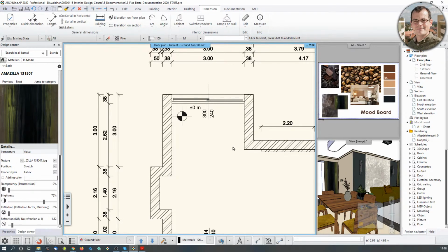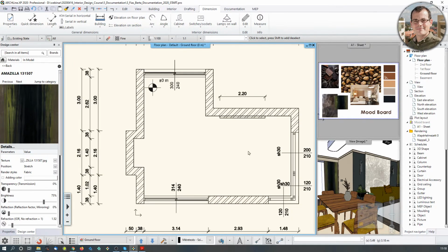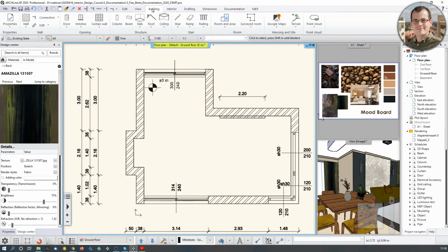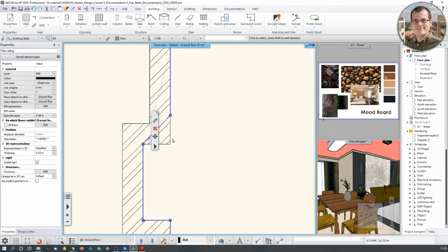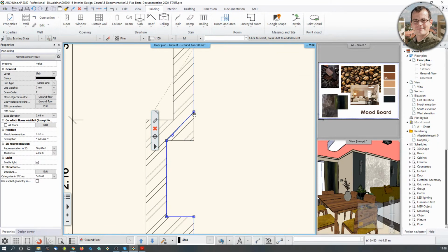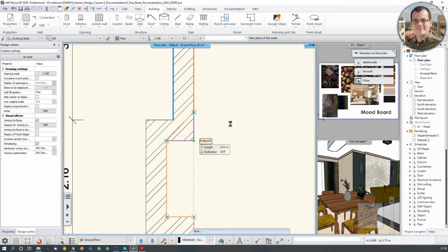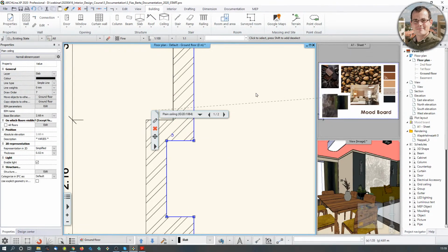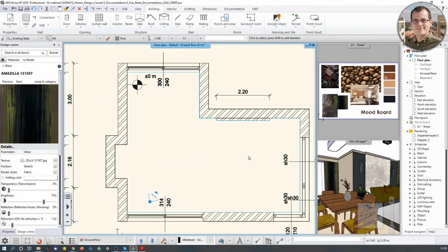So let's start with another. What should be next? I think the room and area stamp would be the next two-dimensional group that we are placing. Now, when it comes to rooms, the software is able to calculate elements which are highlighted or bound by walls. By the way, if I hover my mouse here, you see a very strange sketching problem that I did. The ceiling was made a bit hastily, so this point is not good. If I click on this move node, I can fix that. So that's just a quick detour, so we are not leaving anything unsaid.